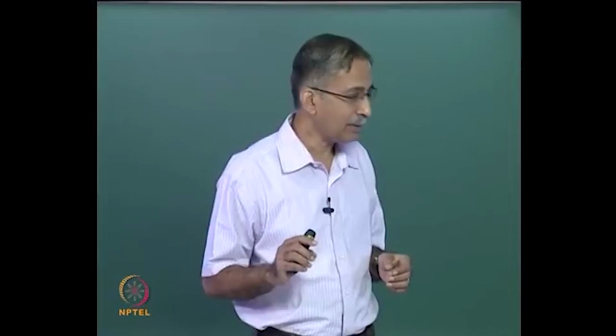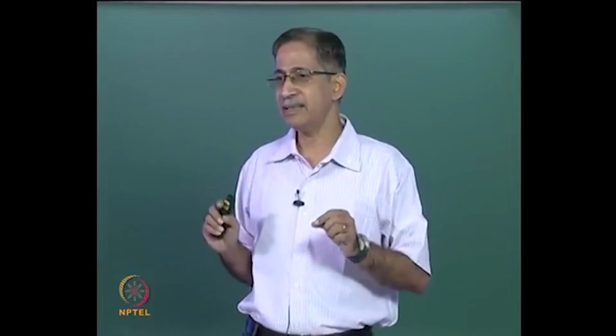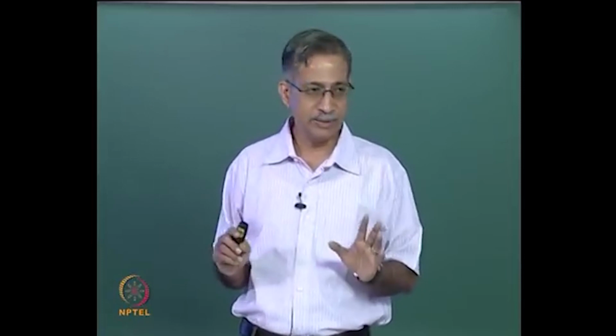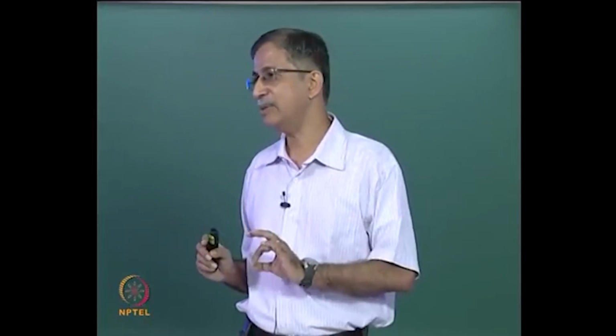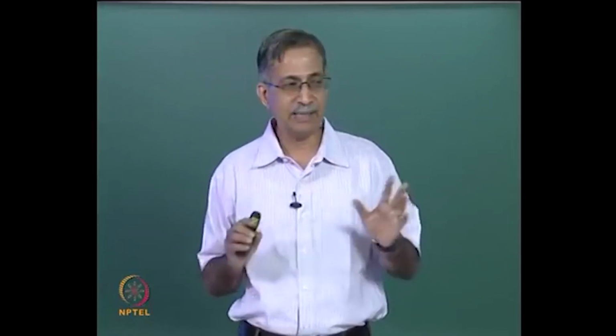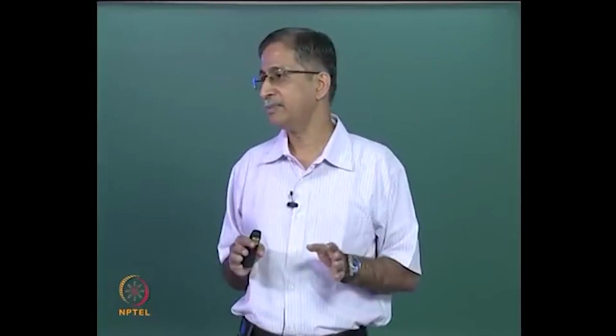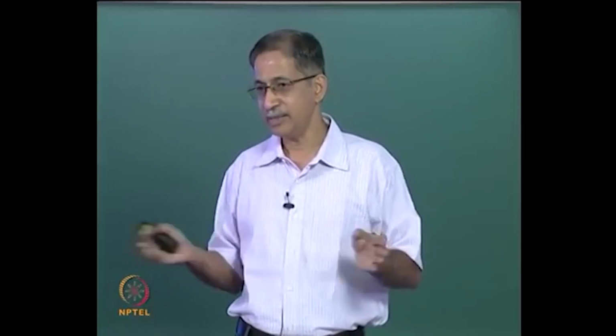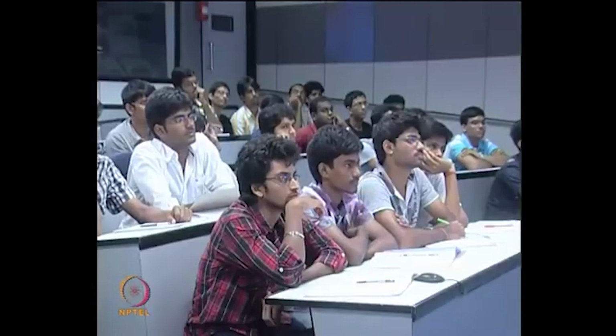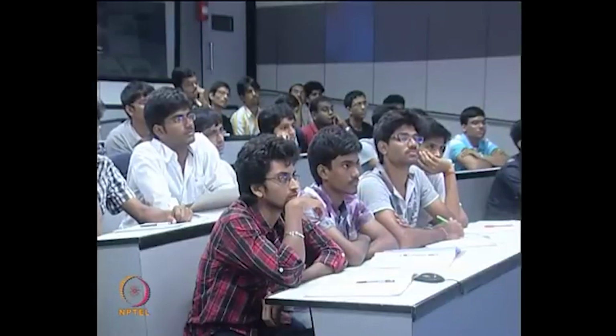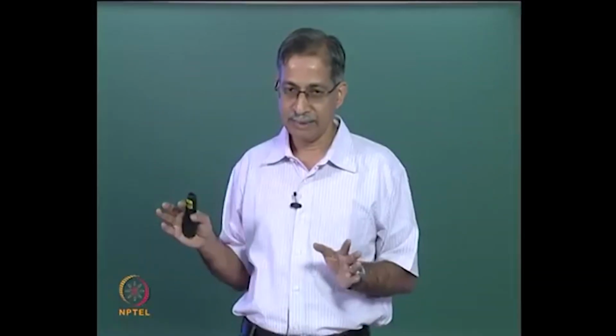Now kinematics is concerned with movements, statics is concerned with forces. So in a truss the movements are joint movements, which are translations in the x and y directions in this example, and the elongations in the different members. Is it clear?